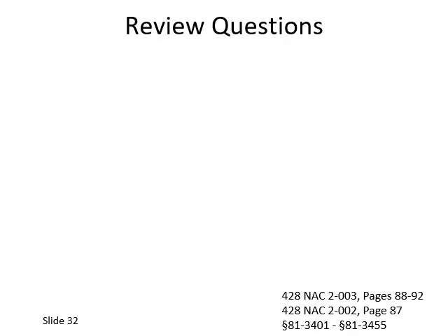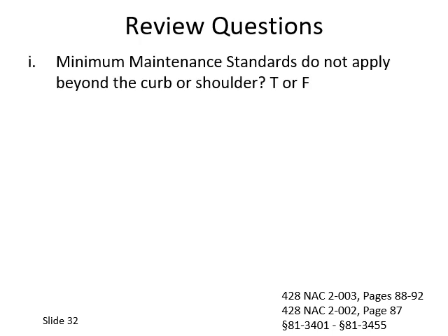Question 1. Minimum maintenance standards do not apply beyond the curb or shoulder. True or false? The answer is false. Maintenance applies to all elements of a highway, road, or street, including surface, shoulders, roadsides, traffic control devices, structures, waterways, and drainage facilities.